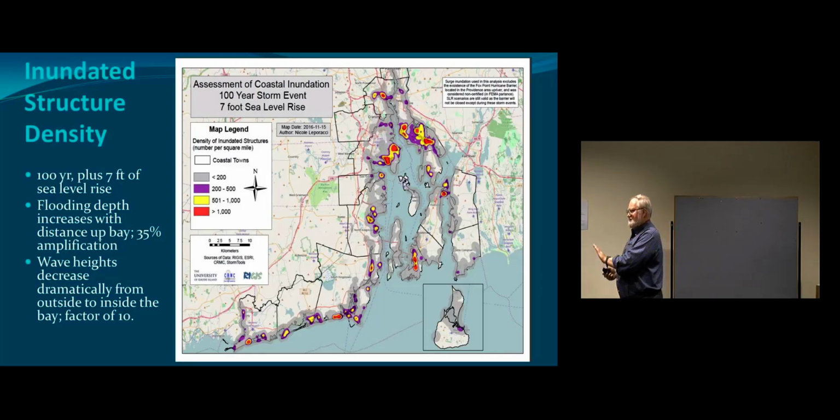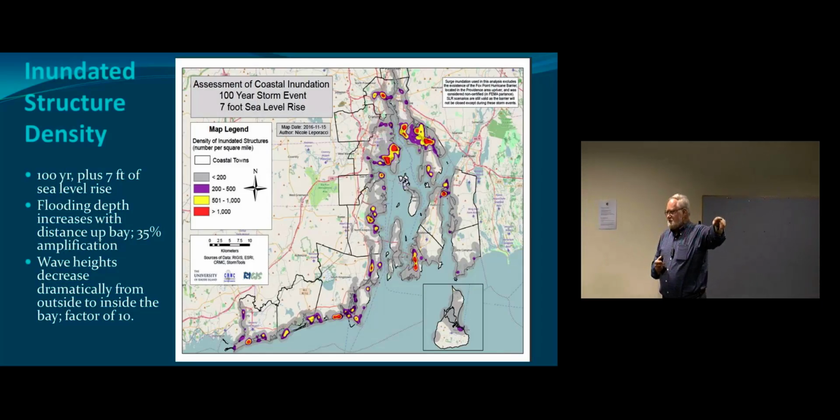Anyway, the center core of the state is a bay with this thing wrapped around, and we are in an area where we have a lot of residential structures. So we essentially did sea level rise calculations, 100-year storm, and we took a look at the complete distribution of housing in that area and created this hotspot map. The hotspot map simply says there are a lot of structures concentrated in these locations that are in harm's way, right? And you look at that and you say, okay, there are some key areas right here, a combination of low-lying topography and really dense populations that are really in harm's way. And there's a bunch of others where the topographic relief is higher, or the distribution of the houses is greater, and so there's less impact. So this is the map we started with to decide which area we would work on.